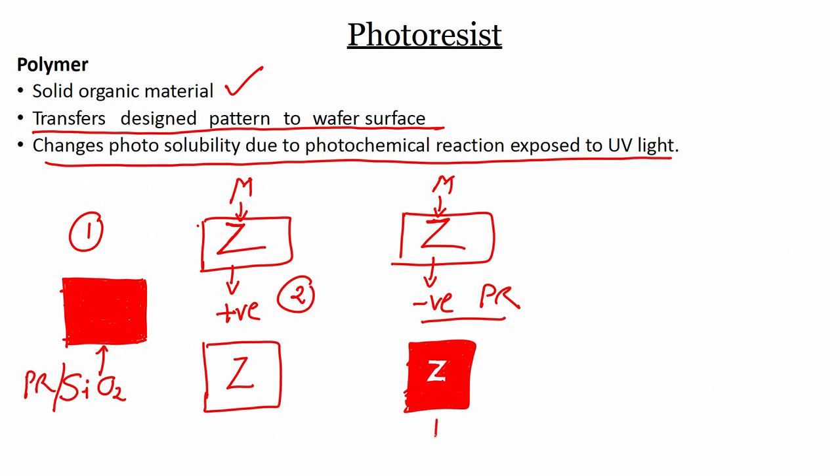That is why you can see that photoresist from the area which was not exposed is etched, is removed. Here you can see that the photoresist under the area which was not exposed becomes stronger. So, this is the example of your positive and negative photoresist.